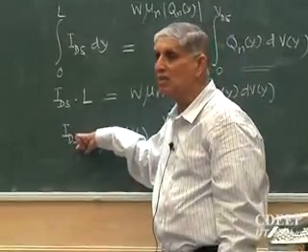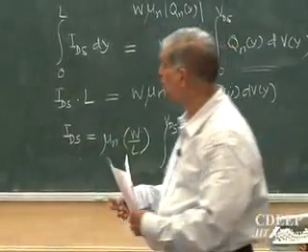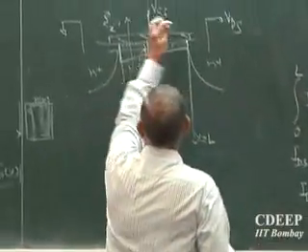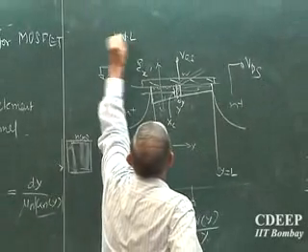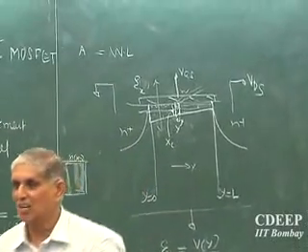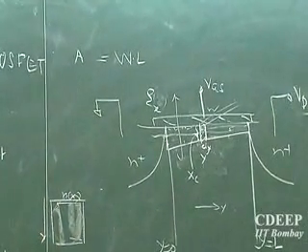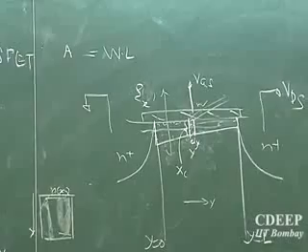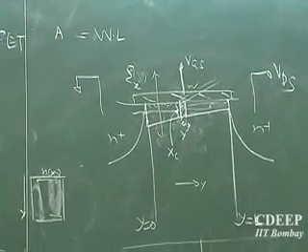But if I do that, what things do I extend? If W by L is larger, the area of the transistor increases, and capacitance is proportional to area, so the capacitance increases. तो एक तरफ आपने करंट बढ़ाया, दूसरे तरफ कैपेसिटर भी बढ़ गया, इसको चार्ज.